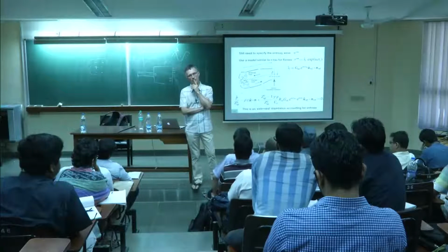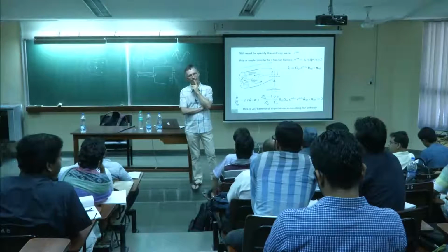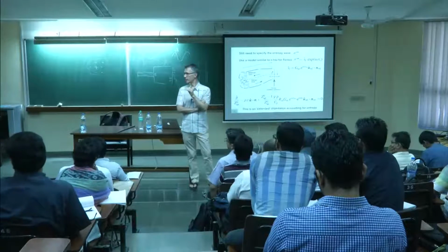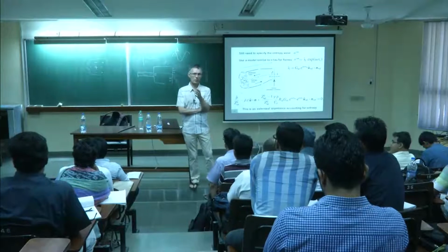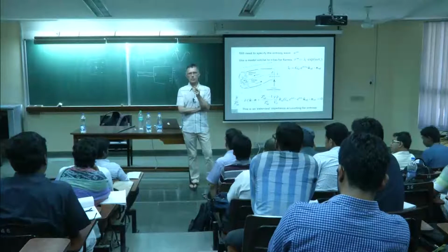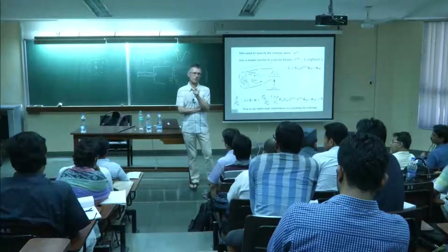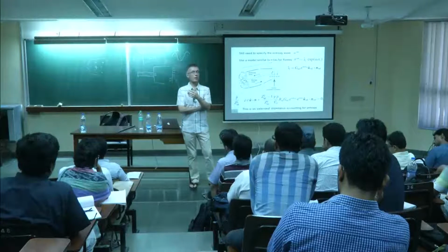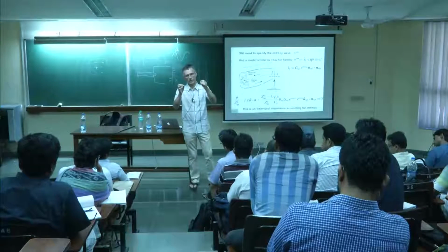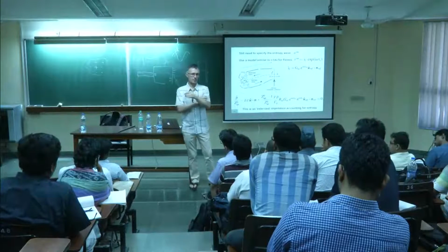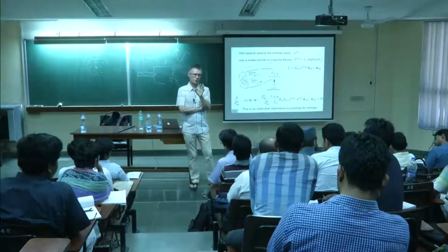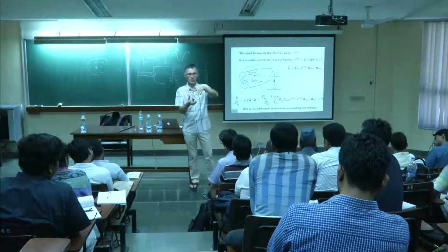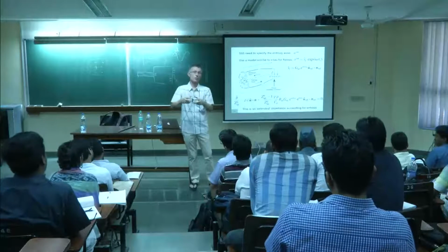How many sensors do they use to predict the transfer function? Well, for the transfer function, in theory, you need only one sensor for Q prime to have the unsteady heat release, and usually one velocity sensor, which is usually LDV. So you can put an LDV sensor upstream of the flame, and you can do it that way. Or you can have 2 pressure sensors, and from that you reconstruct velocity. So the problem of the rocket engine is that the transfer function is not well defined. If it's a transverse mode, there is no transfer function. It has to turn and go in the other direction.